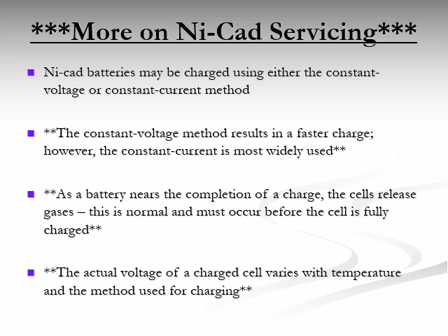It's also important to note that the actual voltage of a fully charged cell can vary depending on both the temperature and the charging method used. These factors must be taken into account when evaluating the state of charge and during performance testing. Understanding these behaviors ensures proper charging, prevents damage, and promotes longer battery life.